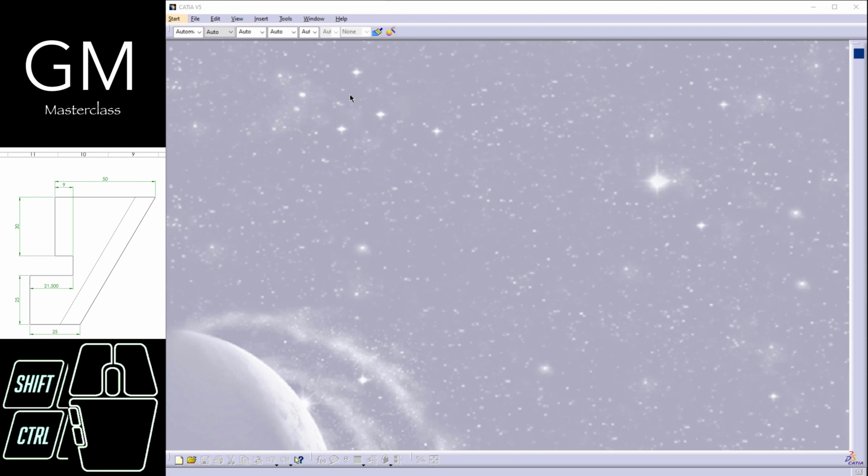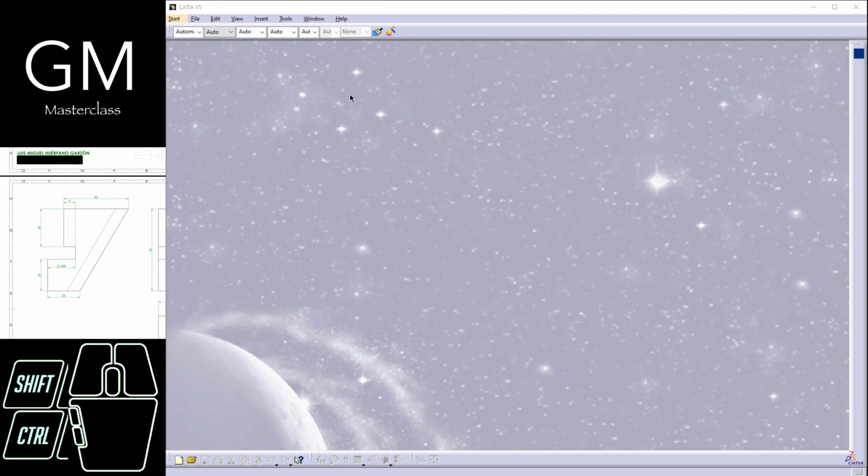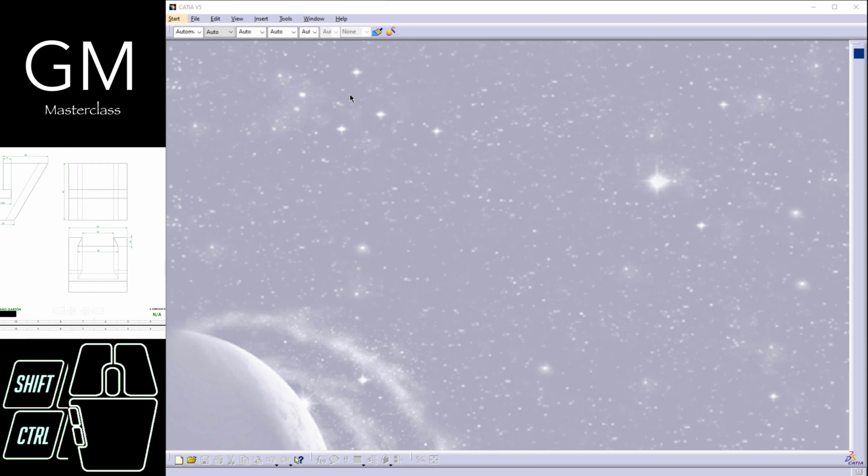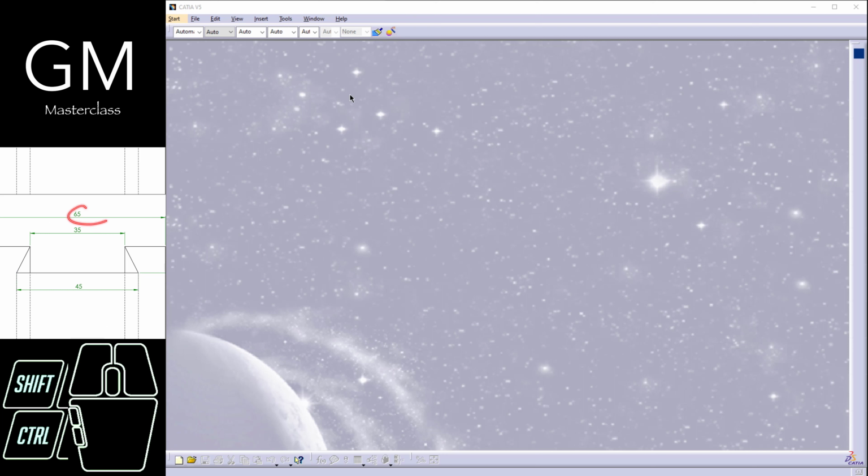Exactly the unit system that it's using. Since I cannot find information about the unit system next to the dimension, then I'm gonna look for it within the engineering draw, maybe in a note. That information usually comes within a box, taking into account the normativity that contains not only the unit system but also the material, the person who did this engineering draw, etc. But since I cannot find information about it, what I can assume is that these are millimeters, right?